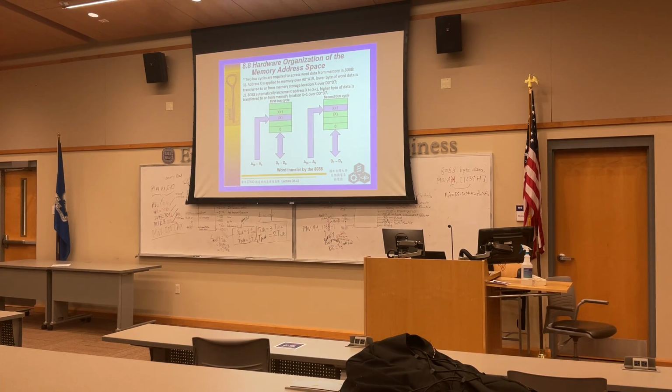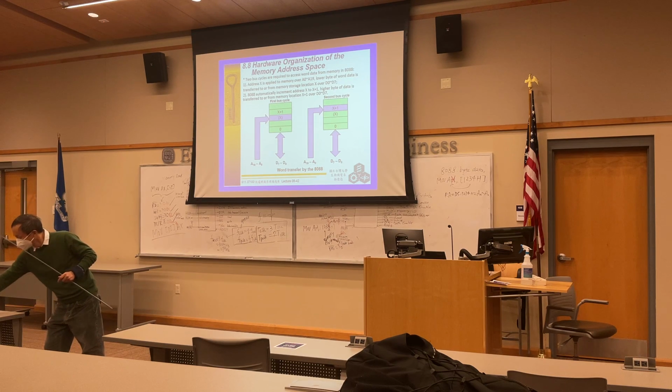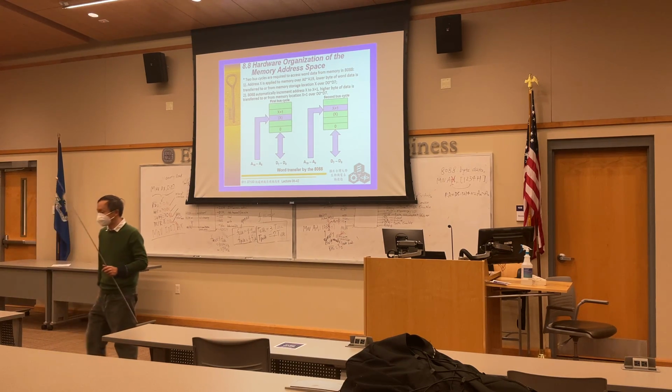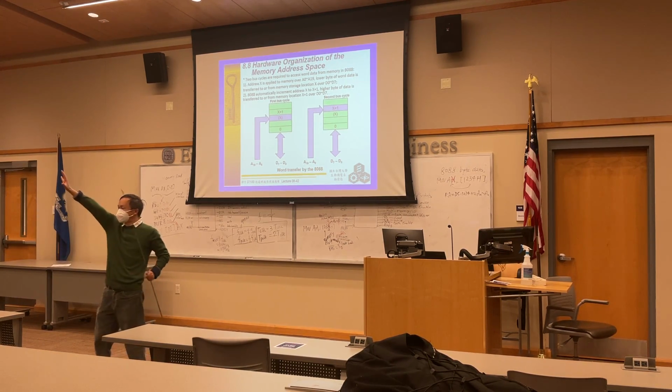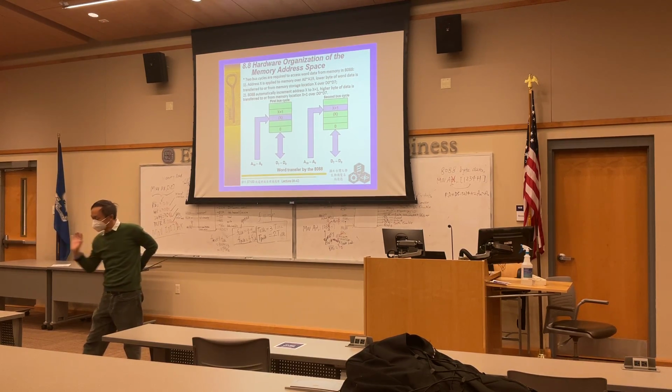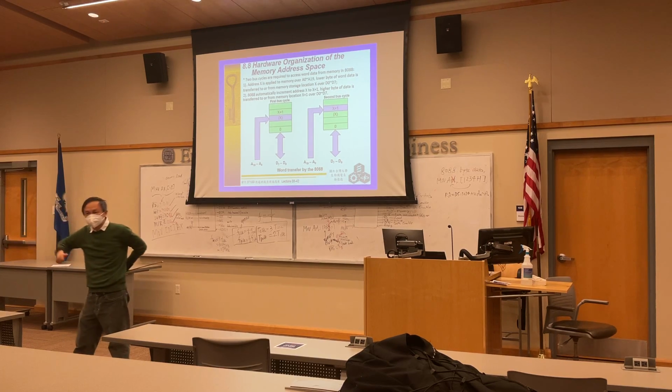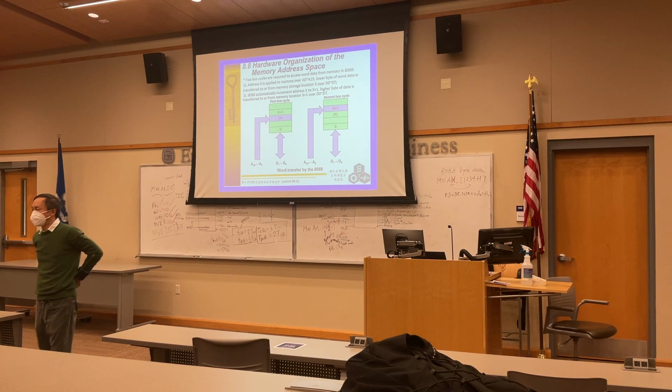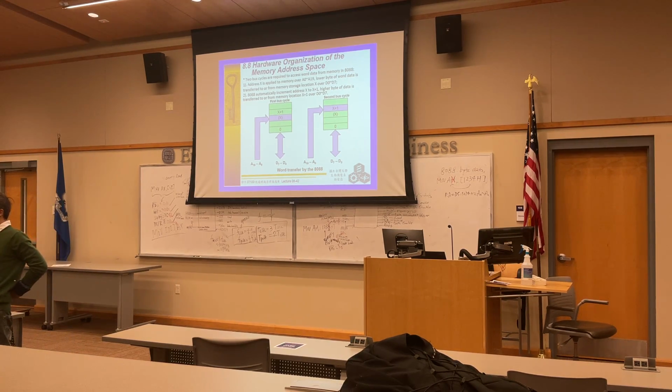Your word data is 2 bytes, so you have to do it one by one. It's like having only one hand: first I reach out for this one, send it to me, and then I increment the address for the next byte, and again reach out and get the high byte. How many bus cycles? 2 bus cycles.